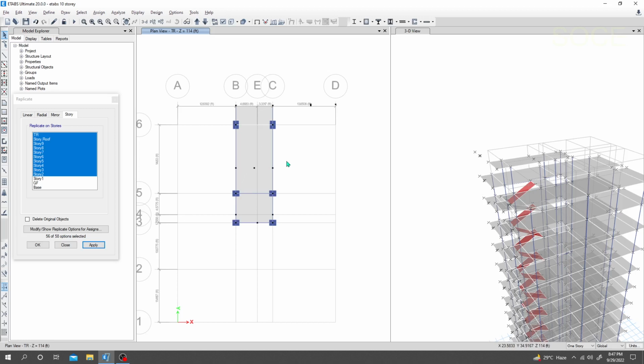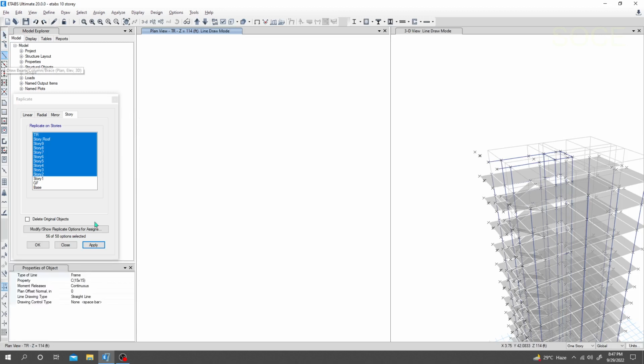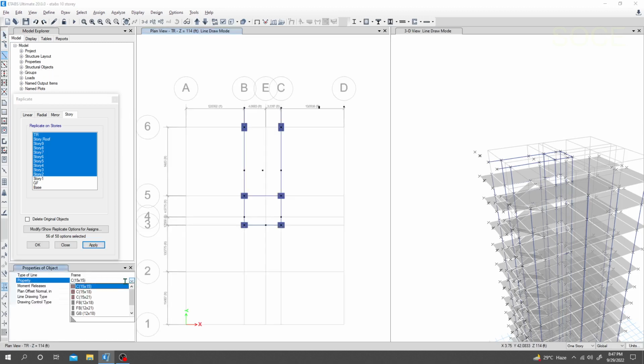So when everything is okay, I'll just go back a little bit. We need a beam here also, right? So I'll go here, and I'll take a floor beam that is 12 by 8 inch for every portion, from that point to that point.